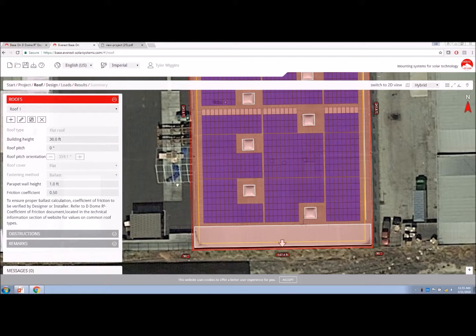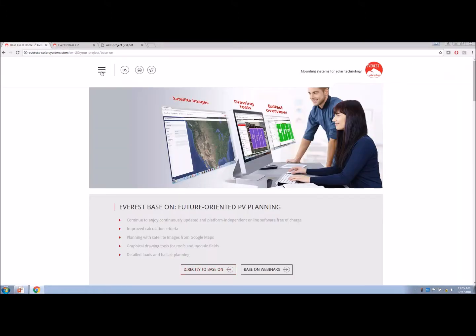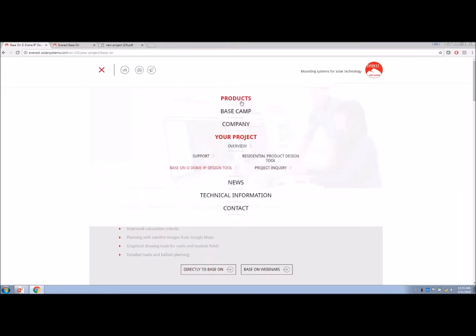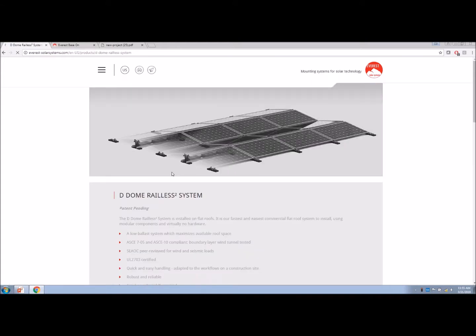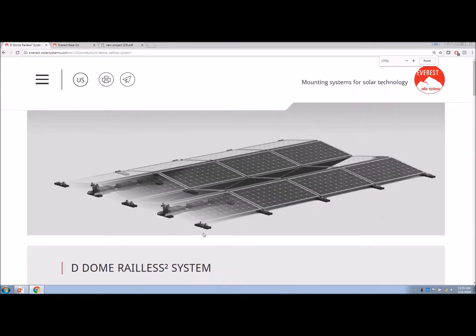What's important is that, I'll bring up a picture to show you, the paver fits in the ballast tray. So there are requirements as far as the paver that will fit. Let's see if I can zoom in here. As you can see, the pavers run along from peak to peak right here. They are 8 inches wide in that direction. If we were placing ballast over the corner strut components, they would be 16 inches wide in that direction.